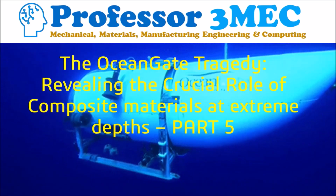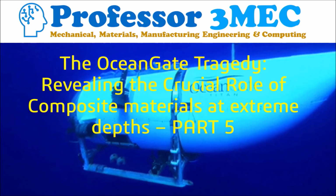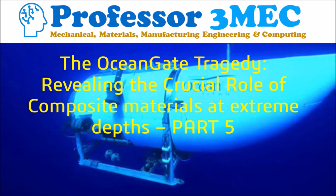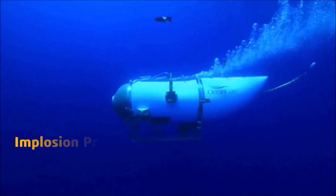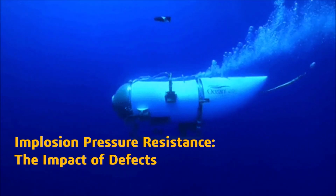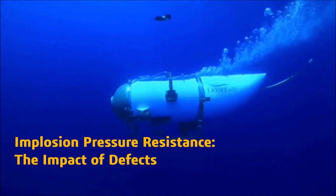In this part, we are looking into the impact of different types of manufacturing and in-service defects found in composites and their effect on implosion pressure resistance. While expressions such as the equations discussed in the previous part can be used to estimate the behavior of ideal cylinders which are under high external pressure, real cylinders always contain defects.